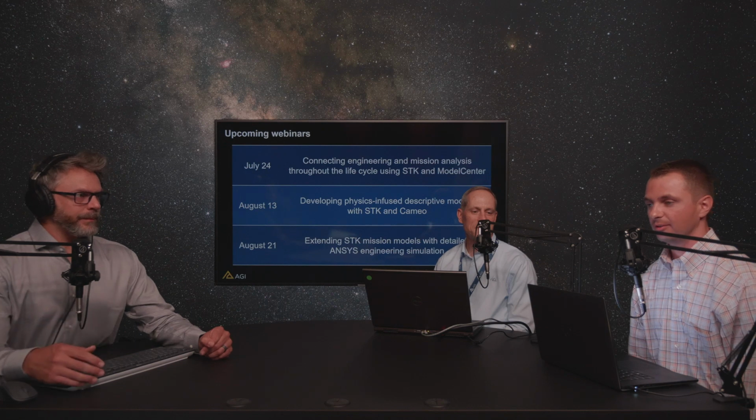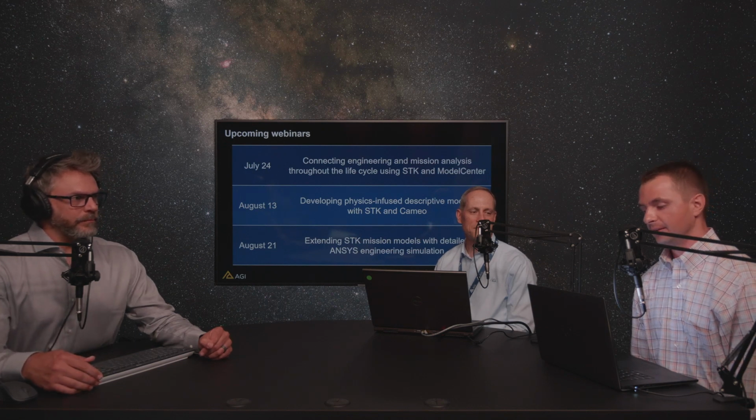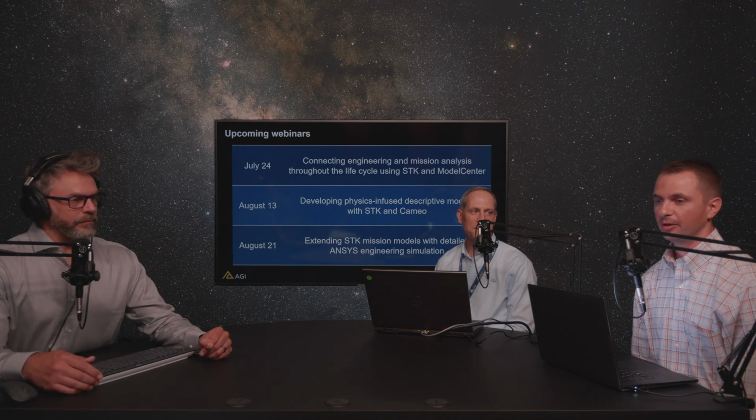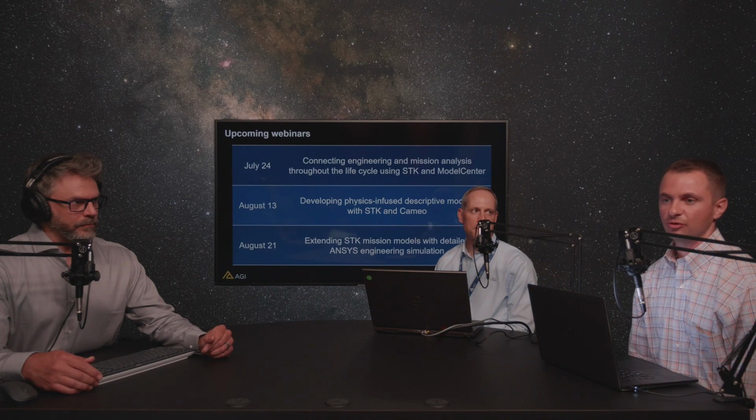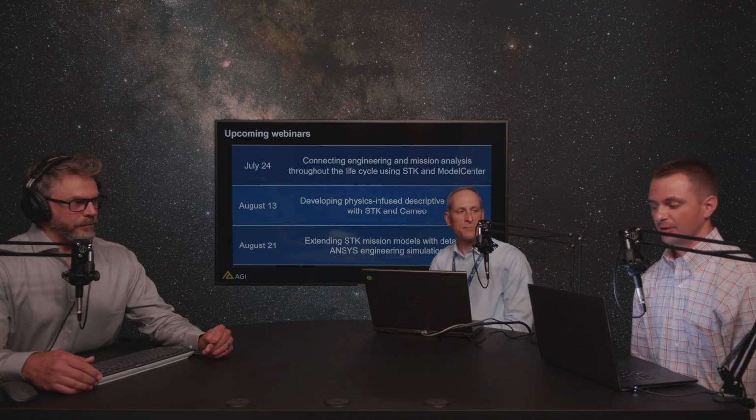And so, for example, specifically the CubeSat example that Kevin showed, what we did within STK, and specifically within Solus, is we reported out the solar flux and Earth albedo flux with respect to each face of the CubeSat. So you're absolutely right. As the attitude of the spacecraft is changing, the different sides of the solar panels will be collecting that power, and you'll have different efficiencies at different angles.